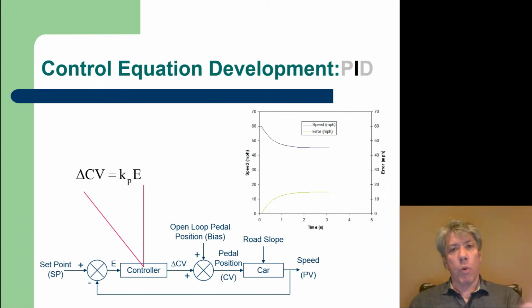And this proportional only controller will multiply any proportional constant, doesn't matter, by the error, which is 0, and it'll say, oh, the pedal can go back to its bias position, right? And if we're still climbing a hill, that means we're doing 40 miles an hour. Of course, that's not what really happens. It settles out to some intermediate balance value where there's just enough error to keep the pedal in a deep enough position so that we maintain some steady state.